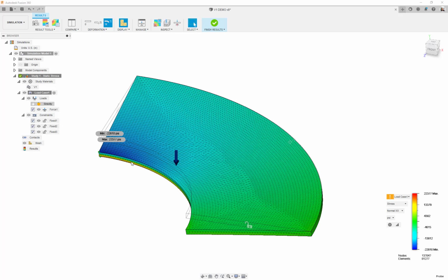Again, it's 12-inch inner radius, 24-inch on the outer radius, thickness of a 1/2 inch if you want to try and replicate that. Modulus at 27.5 E6, Poisson's 0.3, and the load was 942.478 pounds force, and it all looks good.